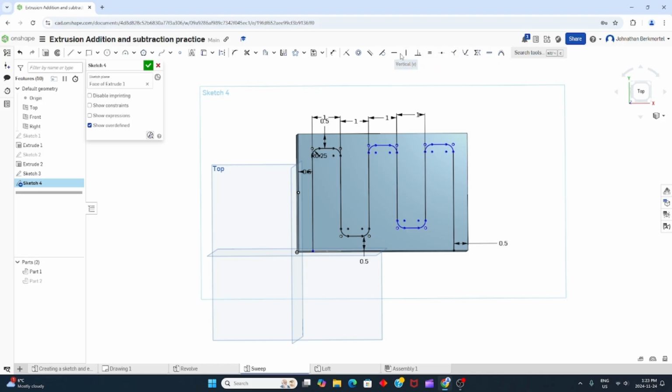Okay, apparently there is no collinear. So if I make these 2 points, so yeah, you could do points, and you could make them horizontal with each other, and they'll give the same result. And pretty much we're just saying that they are in line horizontally with each other.